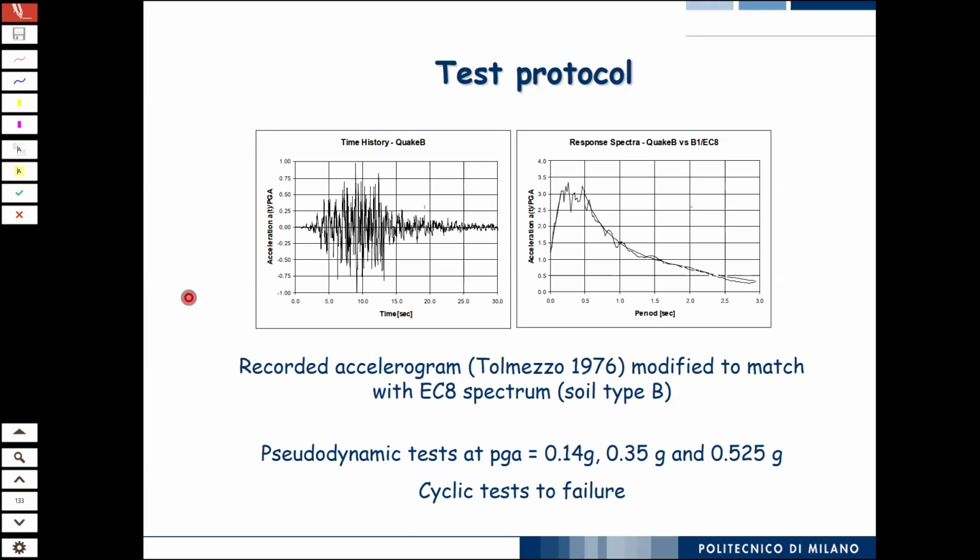And then the southern part, Calabria and Sicily, the tip of the toe of the boot and so on. This one here, if you look exactly, is this divided by 2.5. It's what in the code is assumed to be, if this is for life safety, this is for damage limit state. So this is for ultimate limit state, this is for serviceability. Actually, this one here was 1.5 times this.